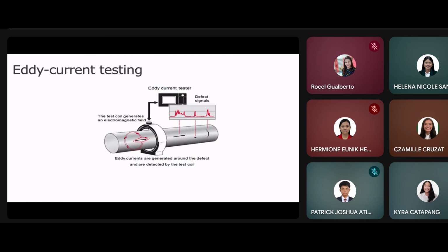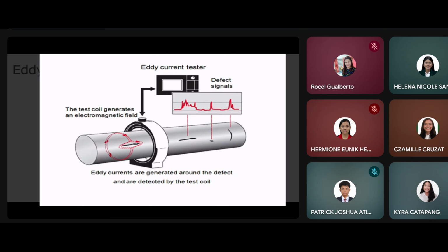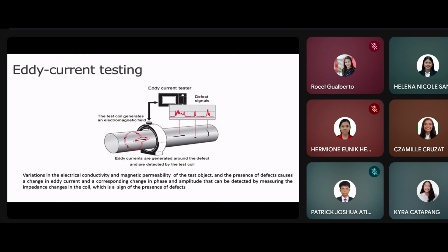The eddy current test is based on the physical phenomenon of electromagnetic induction. In an eddy current probe, an alternating current flows through a wire coil and generates an oscillating magnetic field. If the probe and its magnetic field are brought close to a conductive material like a metal test piece, a circular flow of electrons known as eddy current will begin to move through the metal, like swirling water in a stream. That eddy current flowing through the metal will in turn generate its own magnetic field, which will interact with the coil and its field through mutual inductance.